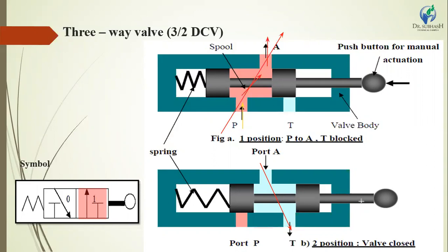The oil is drained from the hydraulic cylinder. This drained oil passes through the direction control valve and is directed from port A to port T. The T port is the hydraulic tank, and we can drain this hydraulic oil into the hydraulic tank.